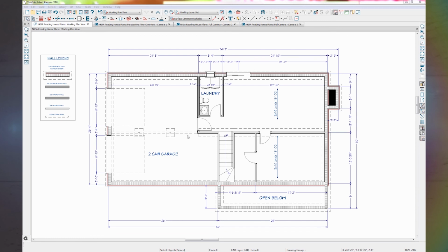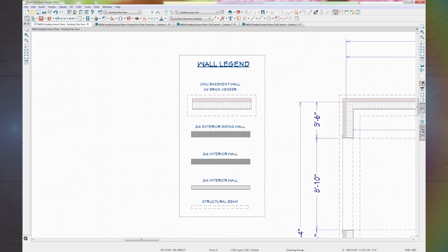This dotted line going through the garage tells us that there's a beam spanning the space. And these two squares indicate concrete footing pads that are supporting posts under the beam. Along with other notes that you'll find in plans like these, it's common to encounter a key like this wall legend. This can make it easier to map and understand the construction methods being used in the design. And that's how you read a floor plan.